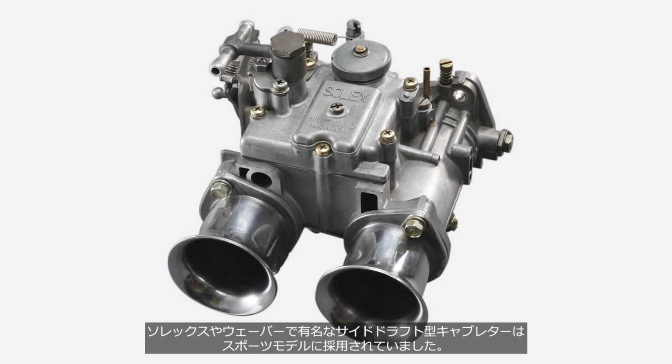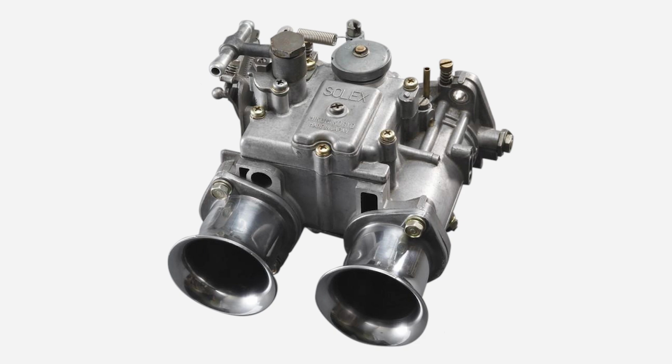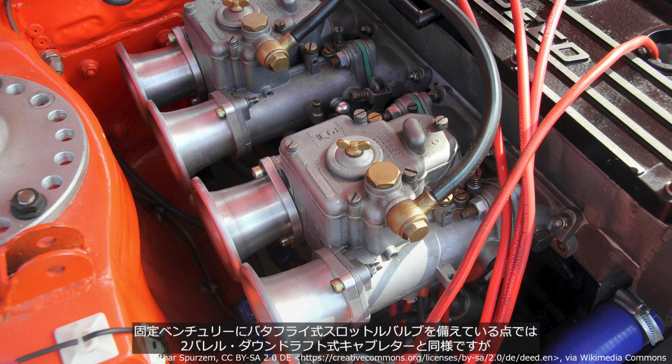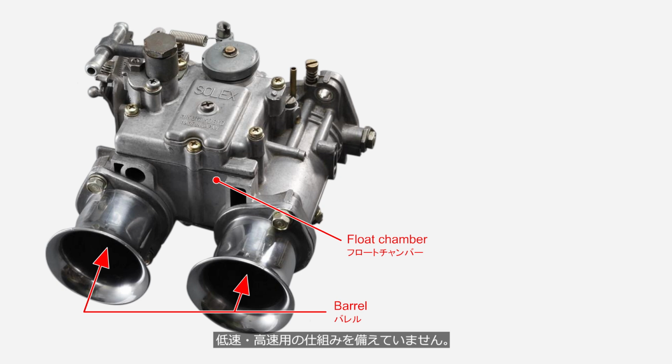The side draft carburetors, made famous by Solex and Weber, were used in sports models. A carburetor is designed for 2 cylinders. For a 4-cylinder engine, 2 carburetors are installed, and for a 6-cylinder engine, 3 carburetors are used. They are similar to 2-barrel downdraft carburetors, in that they feature a fixed venturi and a butterfly-type throttle valve. But they do not have mechanisms for low and high-speed operation.